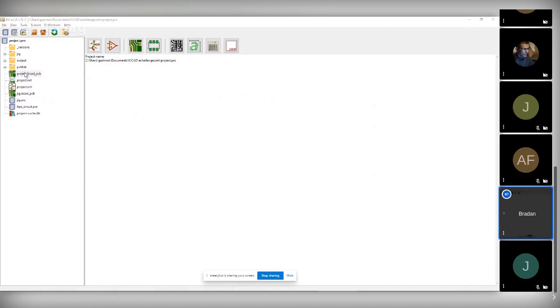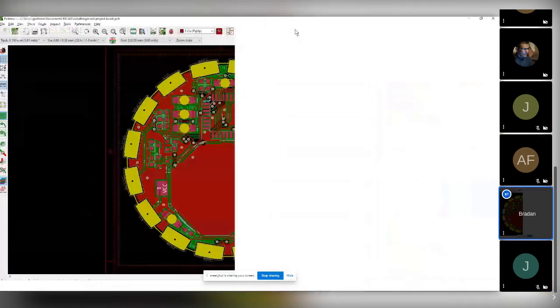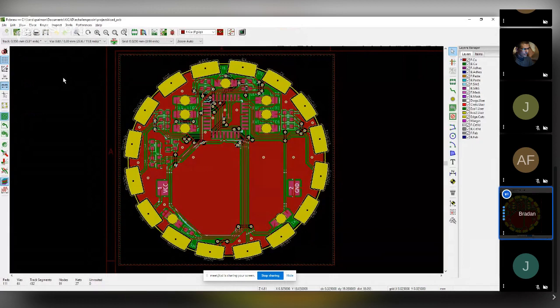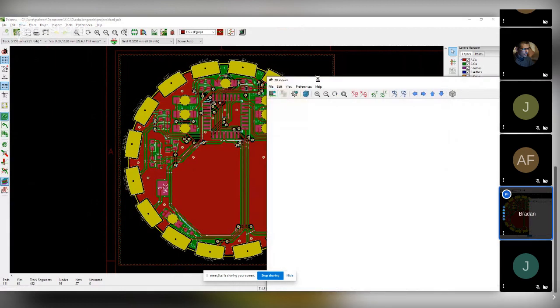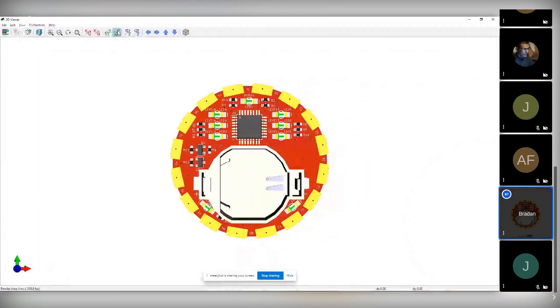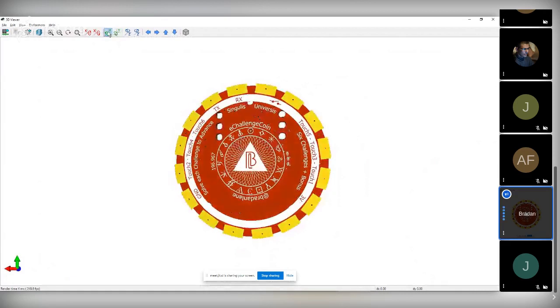This is the project that got me all started on this thing. And this is not overly complicated as far as electronics is concerned, but I needed to have edge plating, and it's a 2 millimeter thick PCB, and there was a bunch of things on this one that were a little bit more interesting and challenging. But this doesn't use any of the removal of mask or the removal of copper, but it was what got me started on doing all the artwork, because I needed to be able to accurately place everything on this one.